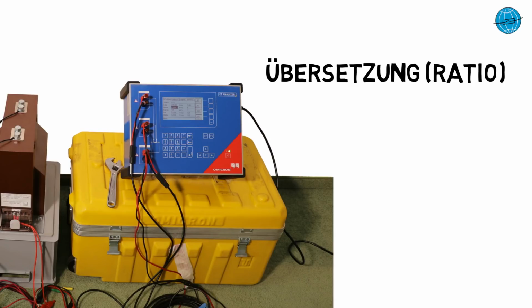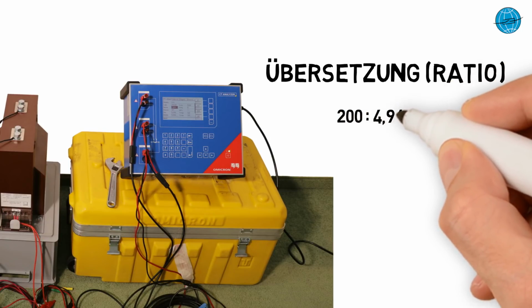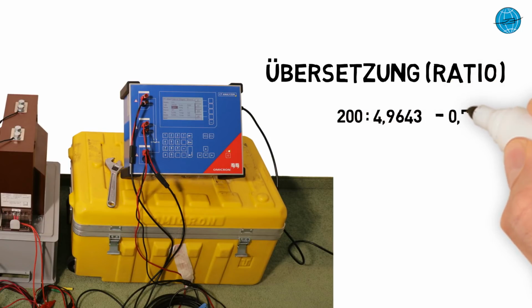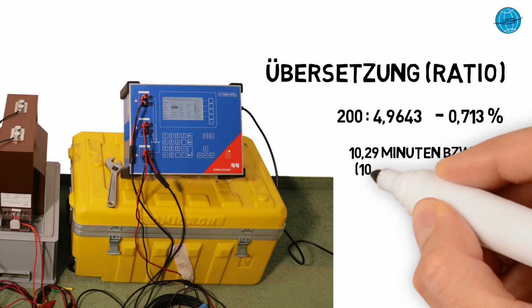For each of our 3 measurements we get the same ratio of 200 to 4.9643 amps with an error of minus 0.713% and an angle error of 10.29 minutes.